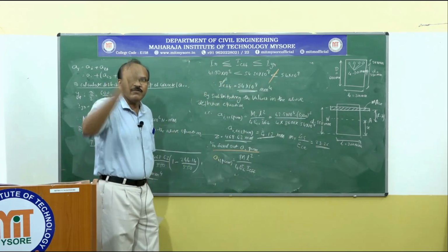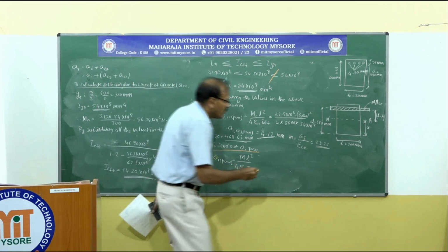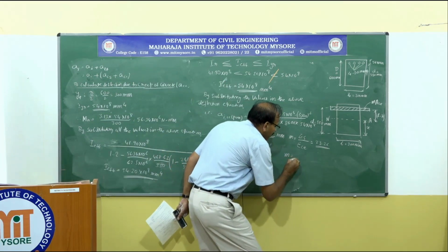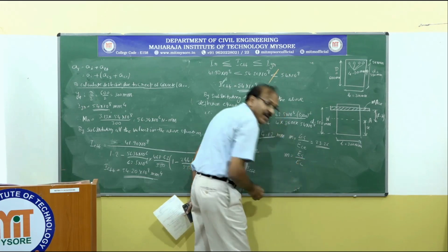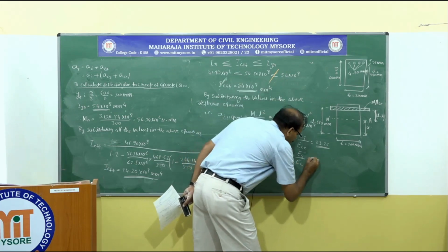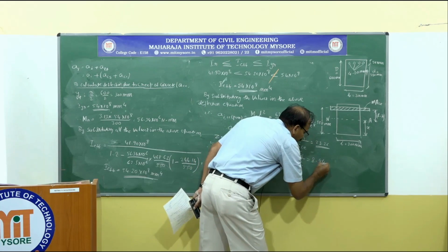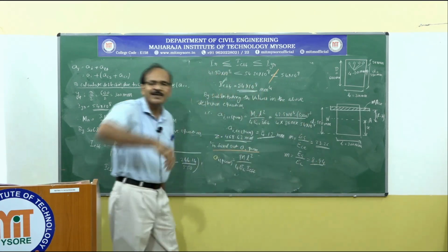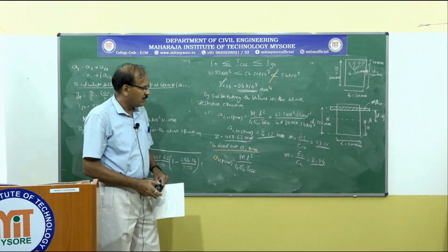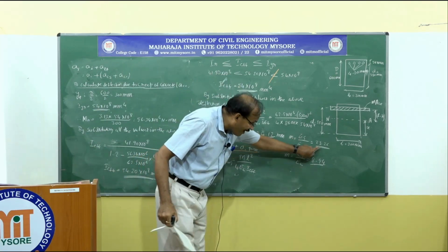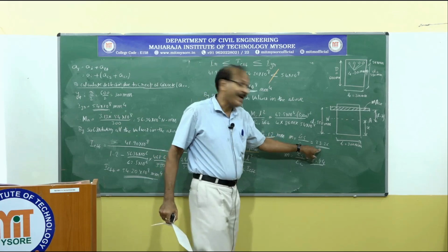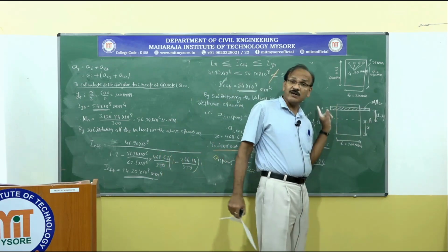But for immediate deflection, to find out the value of M, we are going to make use of ES divided by EC, and we got the value of M equal to 8.94. If you look back in the problem, using this value of M, we calculated the moment of inertia of this section.